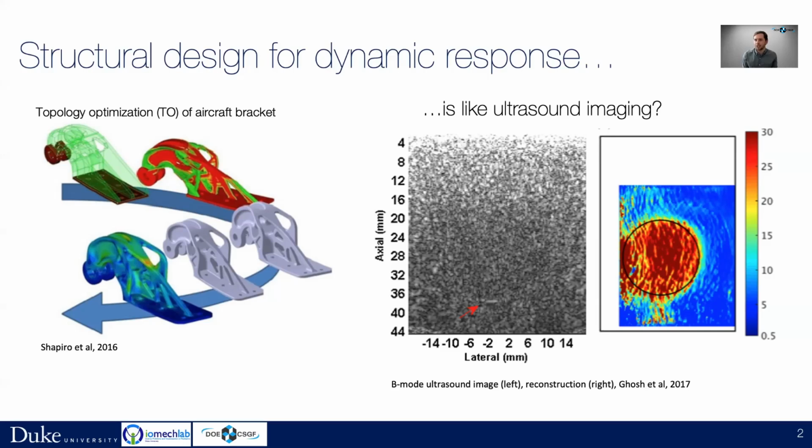We're trying to match the structure's computed response to a desired behavior by determining the optimal allocation of material within the domain. Both problems are posed as PDE-constrained optimization problems, where we try to minimize an objective that depends on the displacement evaluations. These displacements are governed by a set of PDEs that serve as constraints to the optimization problem. And we ultimately use large-scale gradient-based methods to solve these nonlinear optimization problems.